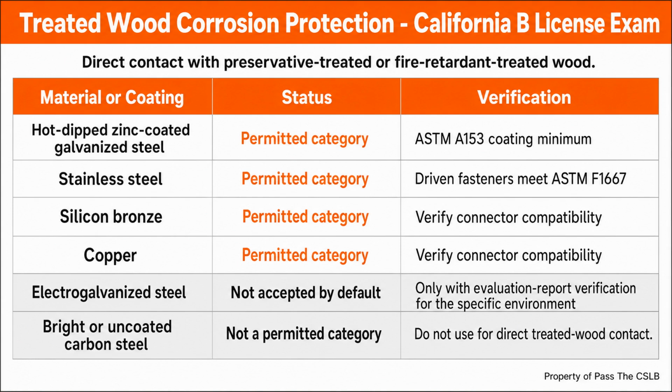Cutting off a leg is not a minor trim. Drilling a new hole is not automatically harmless. Consider a hypothetical shear wall condition where a service line conflicts with a hold-down strap. The tempting shortcut is to bend the strap around the obstruction.